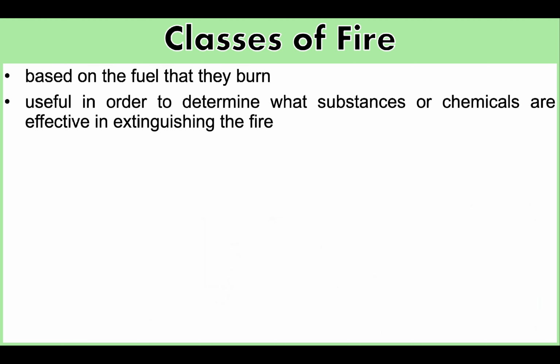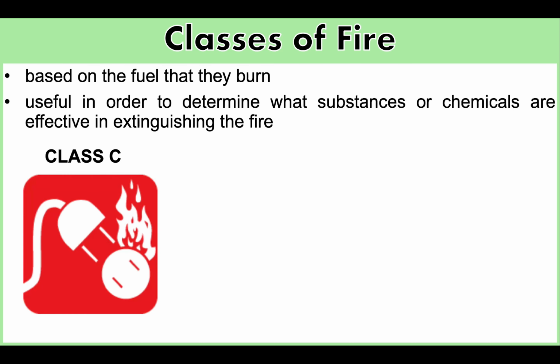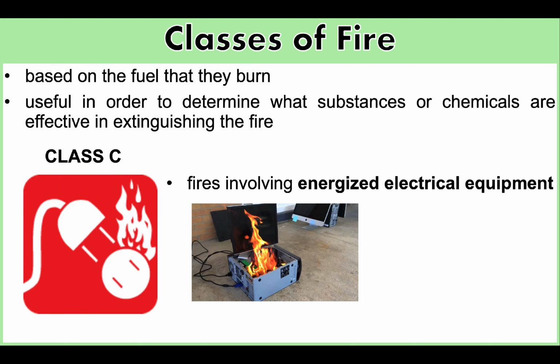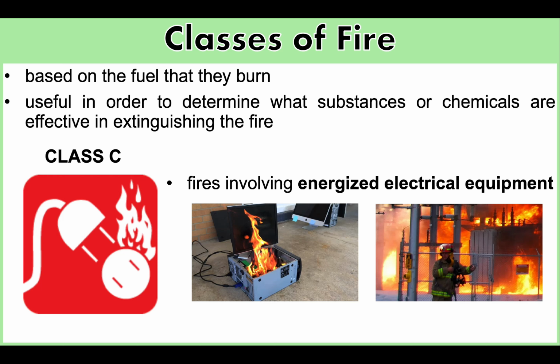Next, we go to Class C fires. Class C fires are fires involving energized electrical equipment such as computers, servers, motors, transformers, and appliances. So take note, energized electrical equipment. If you remove the power, the Class C fire becomes one of the other classes of fire.